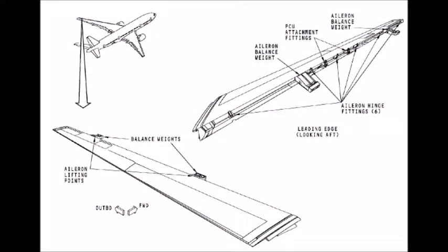Aileron surface. Purpose of aileron surface. The ailerons have two purposes. The ailerons supply low-speed roll control of the airplane. The flaperons and the flight spoilers have this function. Ailerons also move down to supplement the high lift system.